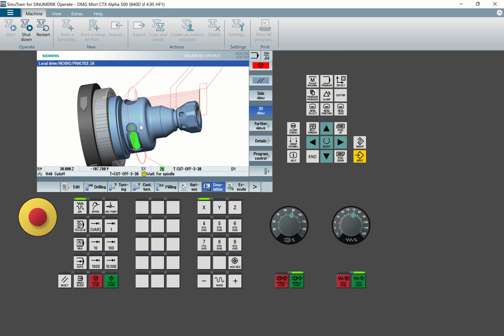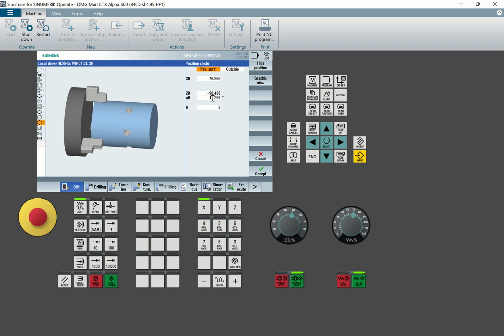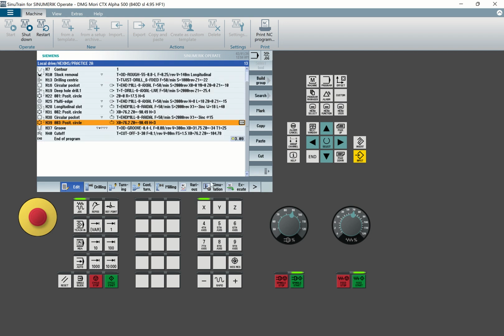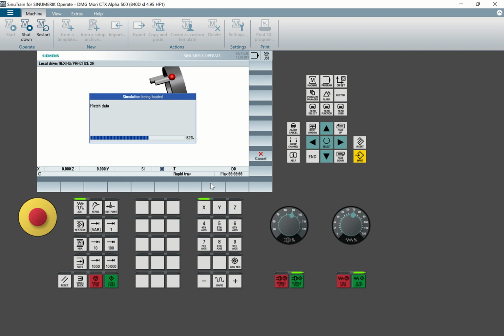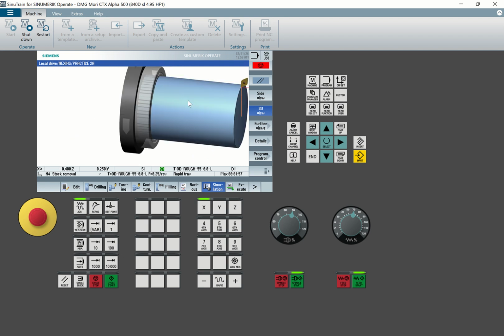So this is how you're able to program. I can even come and change the angle again. So where to change the angle is very important. You can change the angle from this one. For example, this is where you can change the angle. Maybe I can put angle 30, for example. Click OK. Then from here, so it can go to the correct point when it is cutting. So it is good to understand the parameters before you start programming.